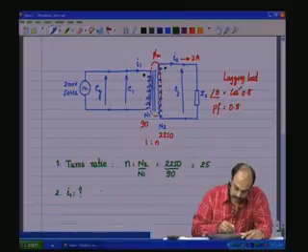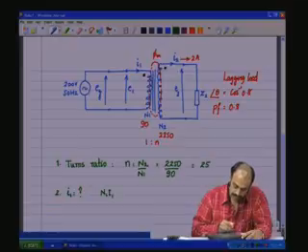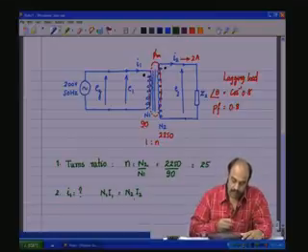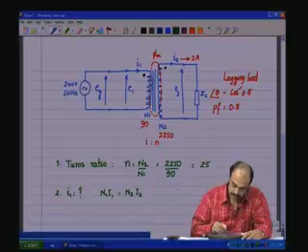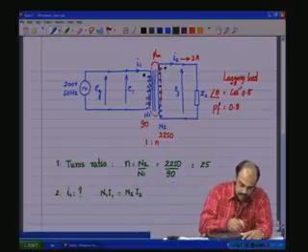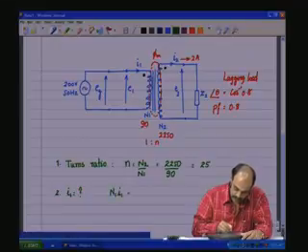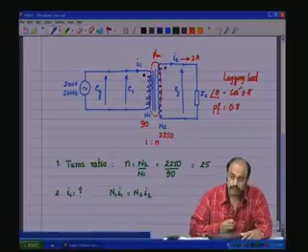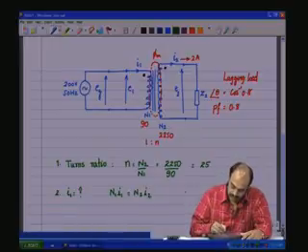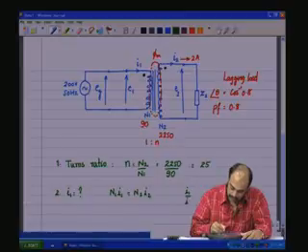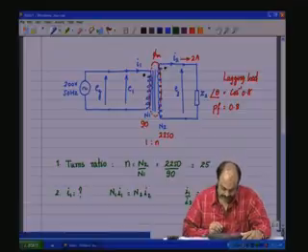So, we know that N1 I1 ampere-turns should be equal to N2 I2 ampere-turns, and also from the power equation we have earlier seen that, let me use the same notations, N1 I1 is equal to N2 I2, because we see that I1 by I2 is equal to N2 by N1, this inverse proportionality for the currents.